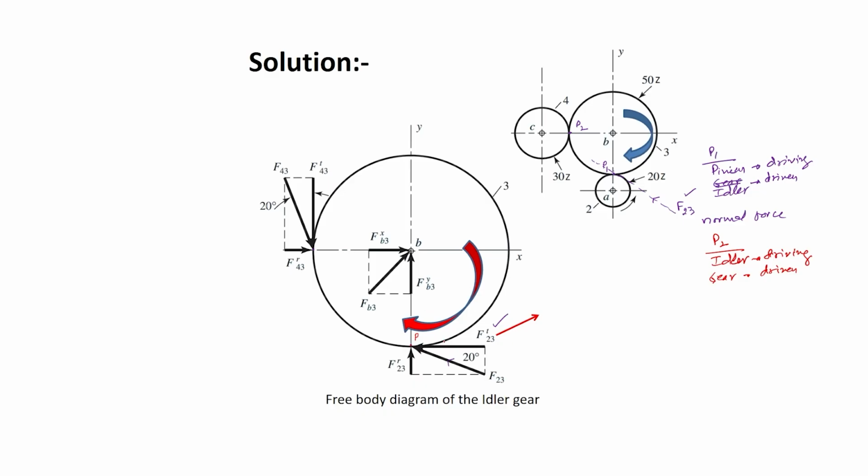The rule is, if the gear is the driving member, then the tangential force acts opposite to the direction of rotation.